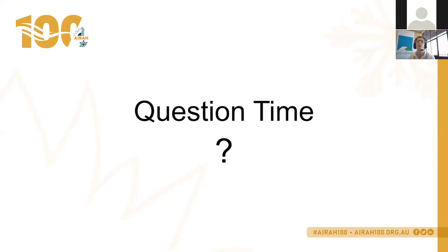Yep, so IAQA is a good source for the building hygienist, definitely. Is the new condensation verification method supposed to be 1D or 2D? It depends on what you're looking at. I think where we're at in Australia is just getting the material layers correct, and that means it's a 1D analysis of layering those insulation systems and the materials. But when you start getting to 2D, that means you're looking at thermal bridges and junctions, say at slab edges and all that sort of stuff, which is still important. But before we even get to 2D, we need to work out what those material layers need to be in different climates for different building types to make them work.